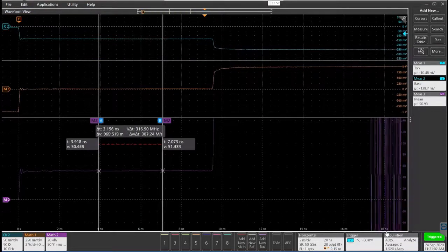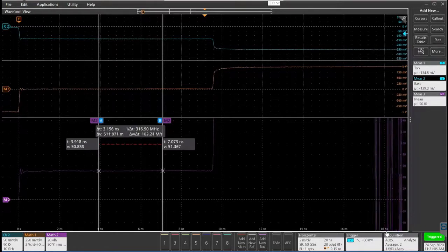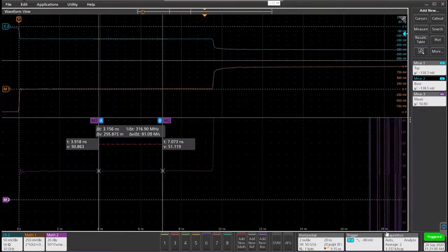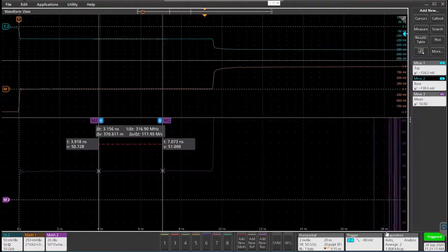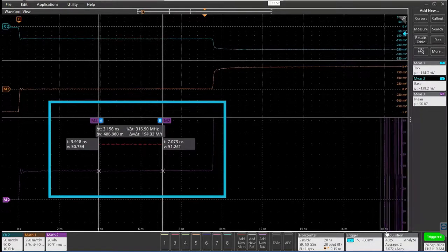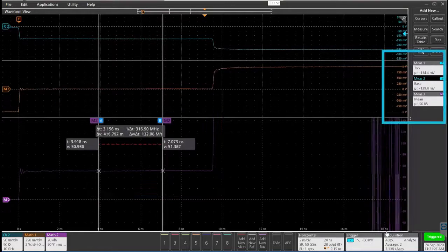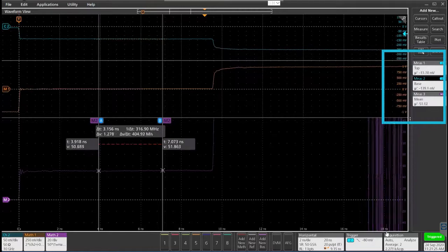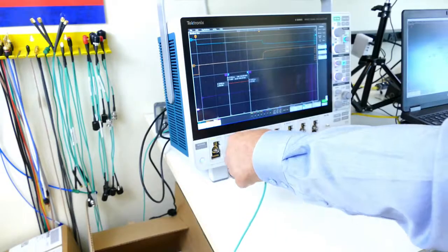The scope math expressions convert that to reflection coefficients, which go from -1 to 1, and a perfect 50 ohm match being 0, and that's the center line. And here we converted it to impedance in the bottom trace, and have a math function that takes the average between the two cursors and displays it here. So this says that our 50 ohm cable is about 50.8 ohms, so that's pretty good.